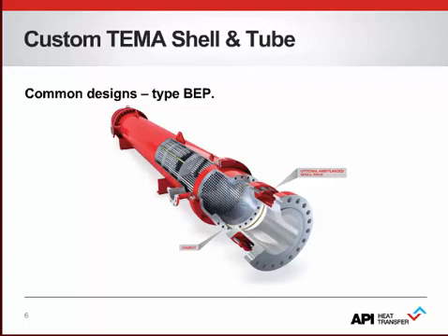In this case, it is also connected to a flanged spool piece for direct bolt-up to process piping. You can see how the tube sheet is sealed against the shell with a packing ring to allow for independent expansion and contraction.